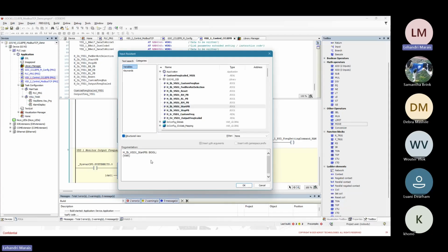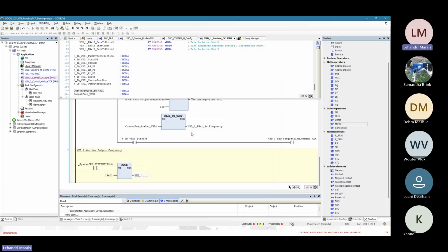And this will be moved to my monitor code register, which is RWW0, monitor code 1 and 2, because this will be set in the lower 8 bits. So if I wanted to set it in the upper 8 bits, I just add 2 zeros at the back of it. But because I want to set it in the lower, I'll just put 0, 1.